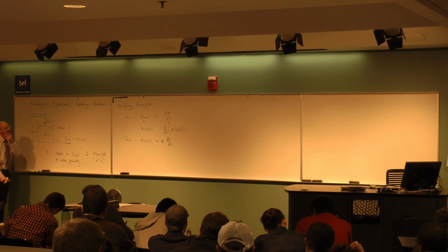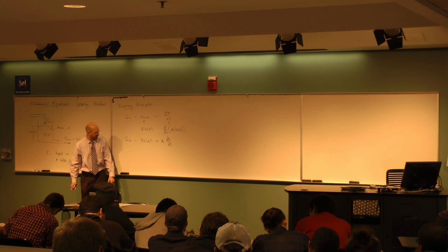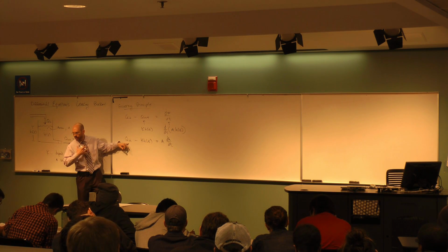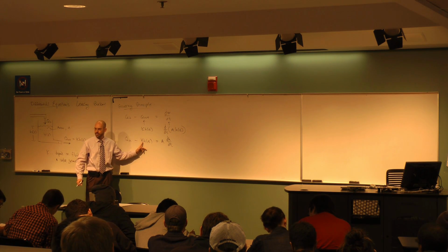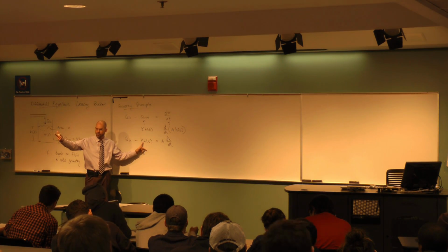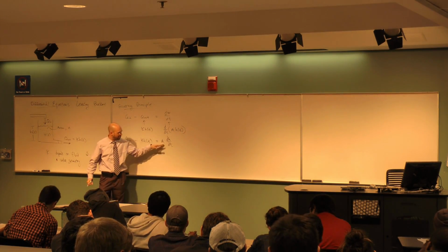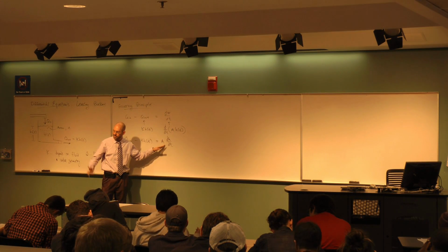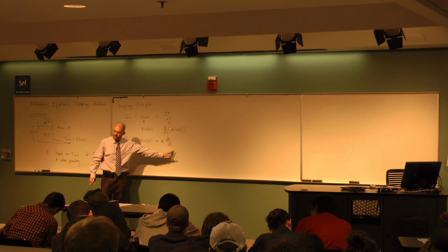So you take a look there, okay, and now what I have is an equation that's got Q in, something I independently control. It's got a problem parameter K, depends on the fluid, depends on the valve. It's got the height, it's got the cross-sectional area of the tank, that's a problem parameter, and then it's got a derivative of the height.